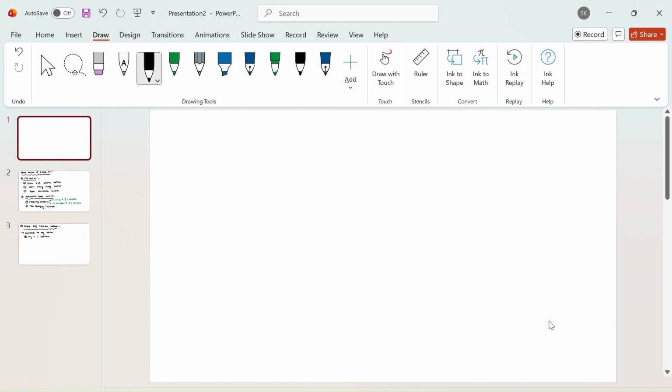As you know, the rotor speed of induction motor is given by Nr equals Ns into (1 minus S). Correct? So to control the Nr, you have two things you can vary. Either you can vary the Ns or you can vary the slip of the induction machine. So there are two techniques. If I talk about it from a broader sense, you can control the slip and you can control the synchronous speed from the supply.